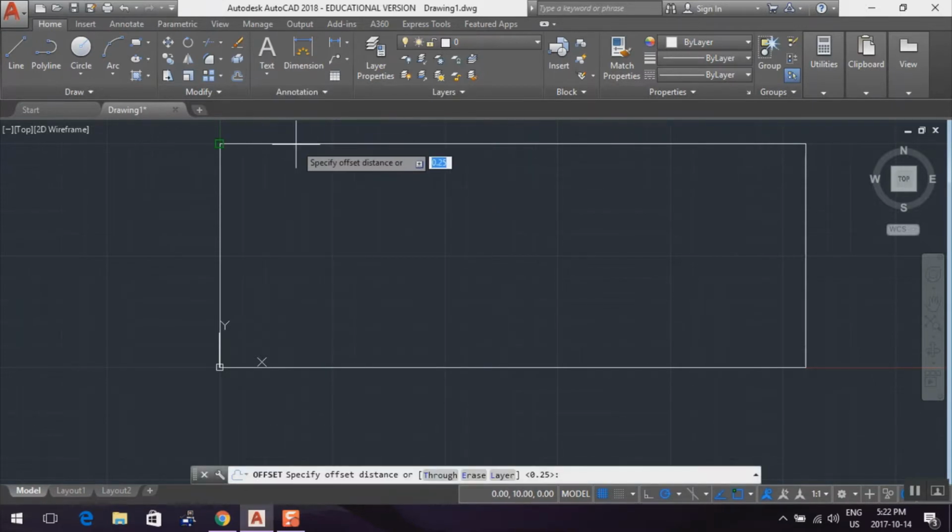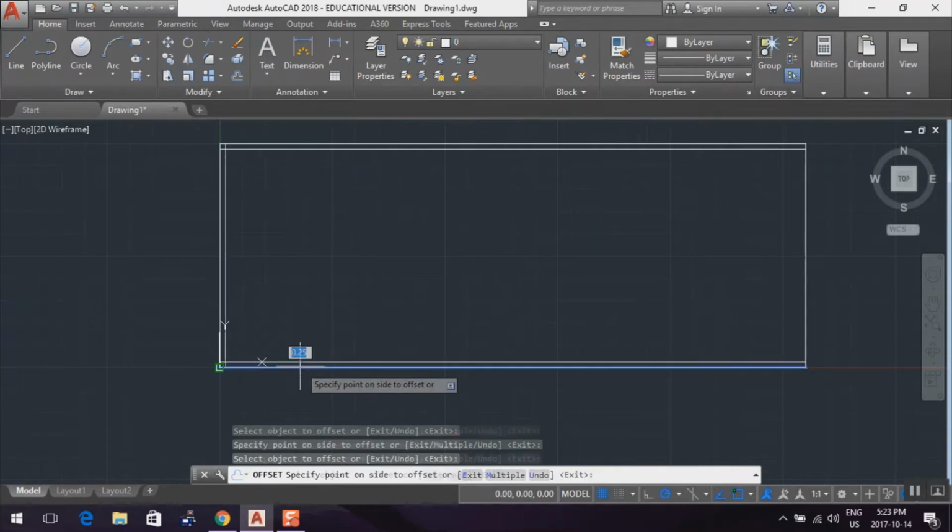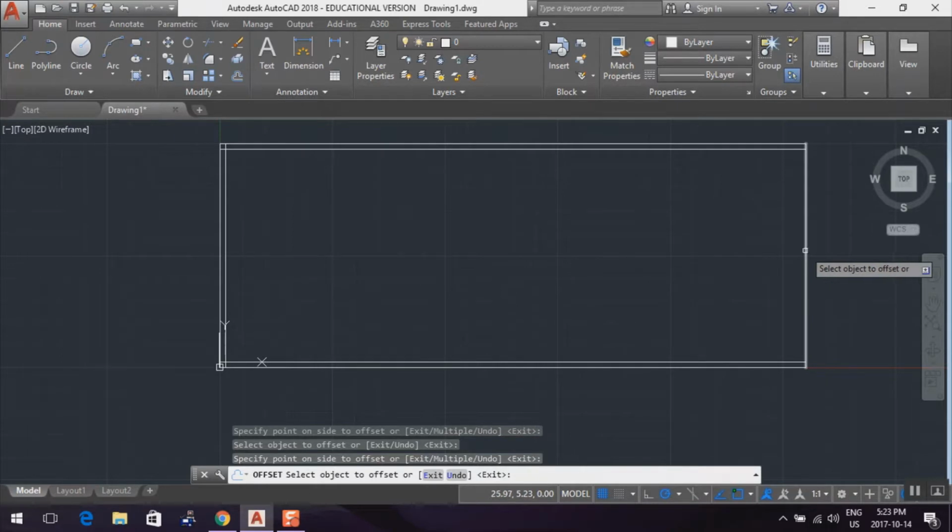Now let's use this offset tool. With the offset tool, when I click on something, first of all, I've got to specify how much I want to offset the line. And our pieces of wood are going to be 0.25 of an inch, so 1/4 inch. So we're going to offset it 1/4 inch. As soon as we click on it and drag in the direction that we want to offset it, I could drag to either side, it automatically does it 1/4 inch for us. And I just have to click and then it happens.